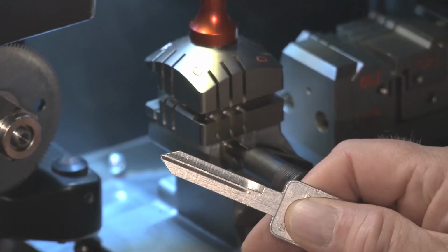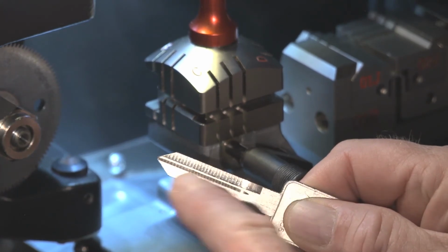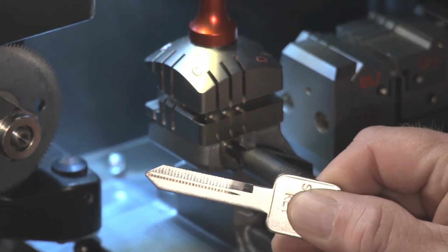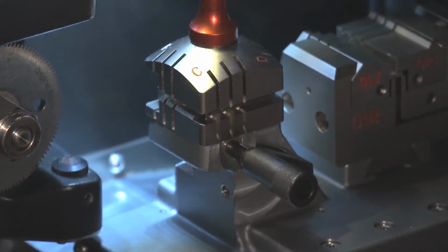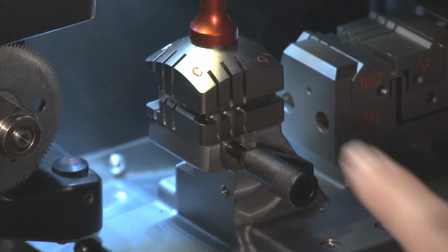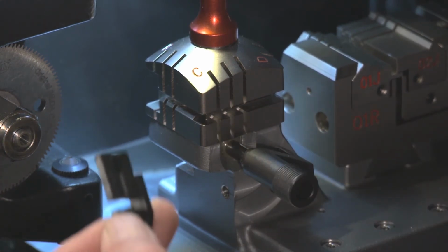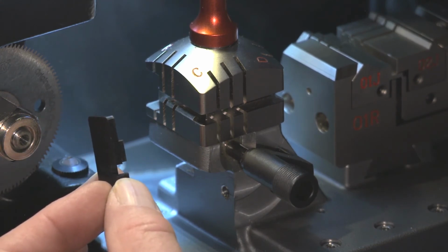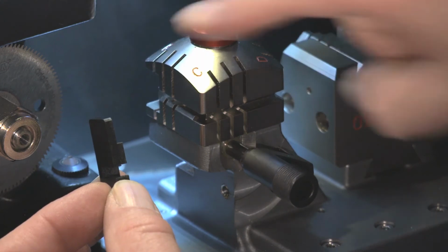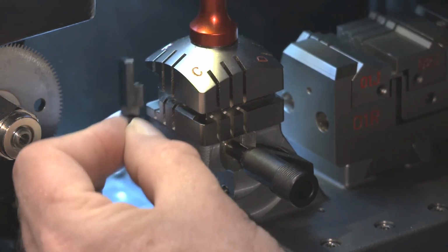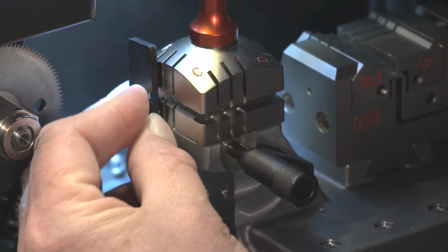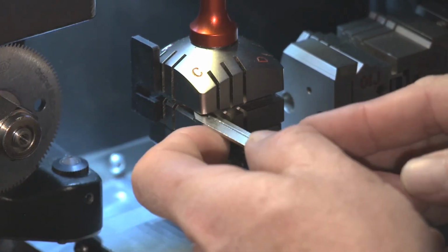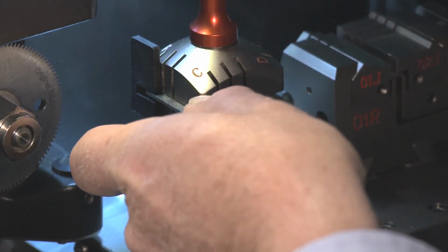Notice that with this particular key, the milling groove runs down the center of the blade on both sides, so I can use either side C or D. In this case, I will be using side C to clamp the key in the milling groove. Since this blank does not have a shoulder, it will be gauged using the tip of the key blade. The stop position shown is 4, located at the back of the clamp, so I will use the Stop 4 tool. Place the tool onto the clamp so that it fits into slot 3, allowing you to slide the key into the back side of the jaw, Stop 4.